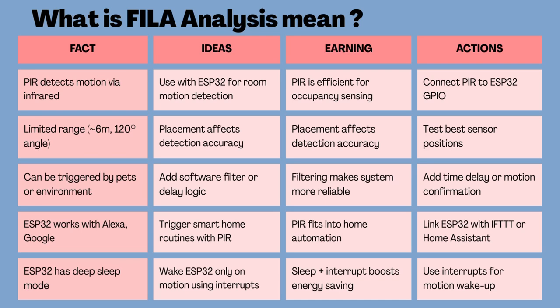For the last fact, ESP32 has deep sleep mode. For the ideas, wake ESP32 only on motion using interrupts. For the learning, sleep plus interrupt boosts energy saving. For the action, use an interrupt for motion wake up.